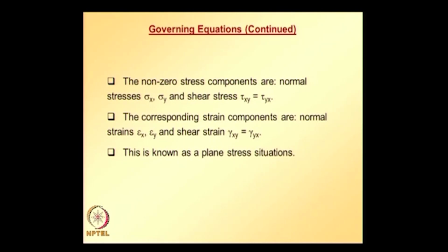And please note that even though out of plane stress components are 0, out of plane strain components are not necessarily 0. Note that strains epsilon z, gamma y z and gamma z x are not necessarily 0.